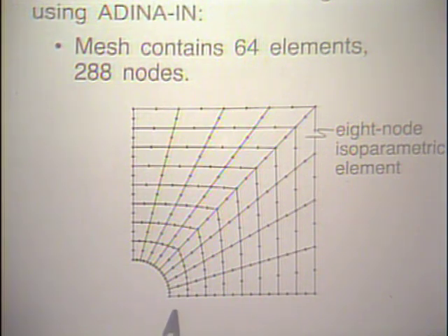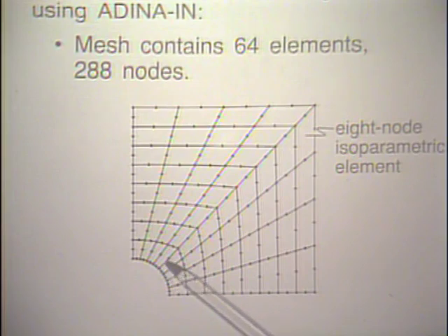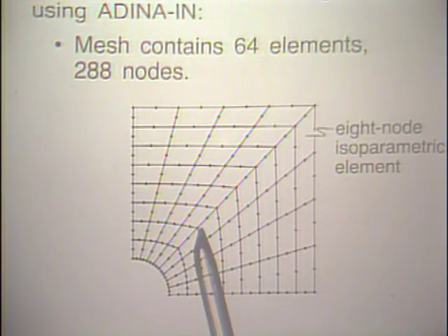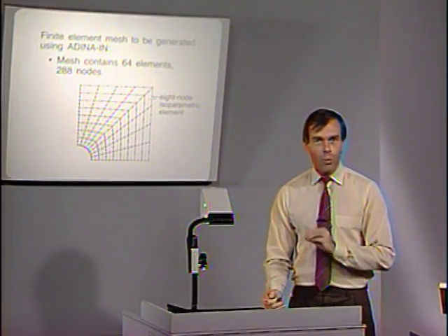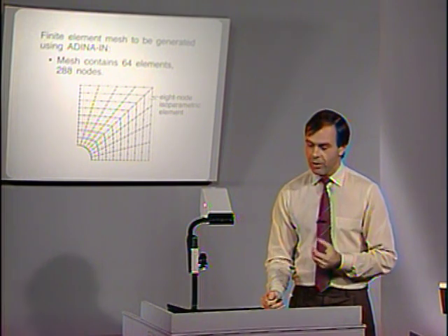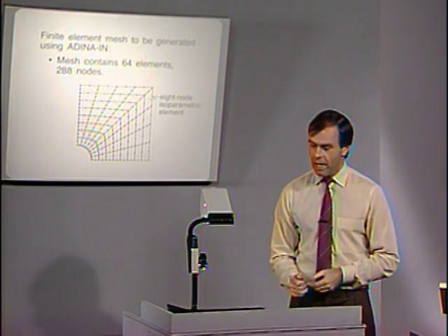In particular, for the analysis that I'd like to show you in this final phase, we have plotted stress jumps along these two lines. Now notice that, for example, at this node here, we have 4 elements coupling into this node. So at this node, we get 4 different stress predictions for each stress component. At this node here, we would have only 2 stress predictions for each stress component because only 2 elements couple into this node. That is one way to evaluate how accurate our results are.